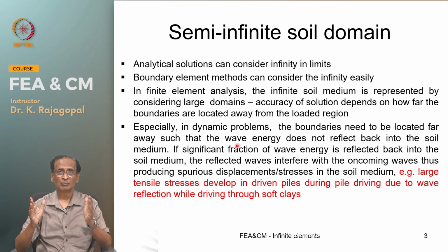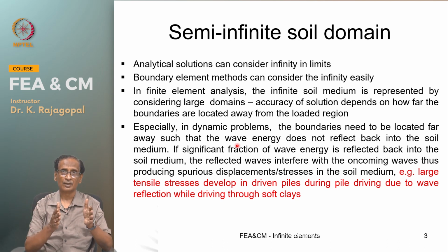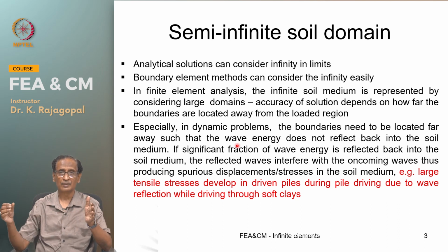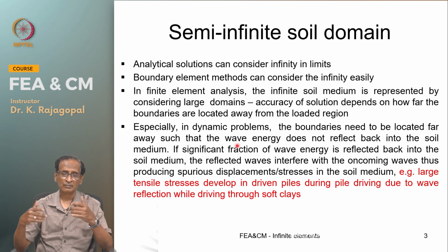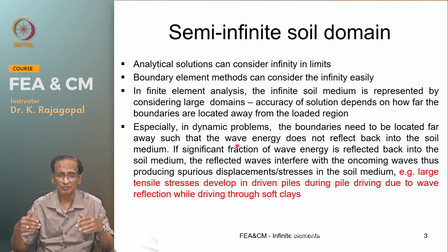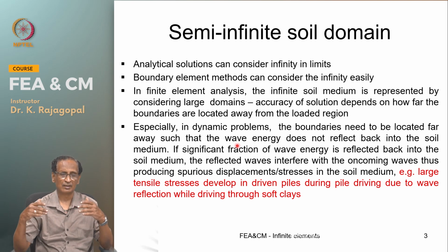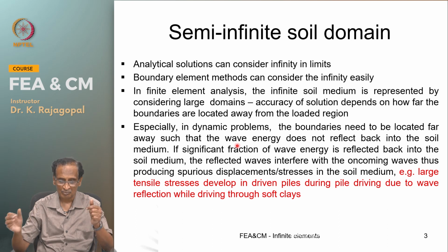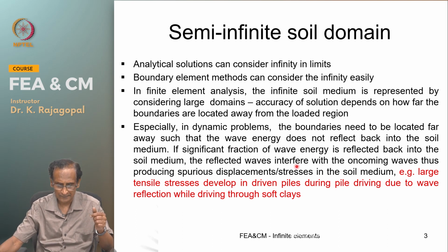But if you place the boundary too close, also you will have a problem, you will have some numerical influence, like your waves may be propagating. Once they reach the rigid end, they will reflect back, and then your oncoming wave and the reflected wave might interact, and they might produce some other extraneous stress condition within the soil, and that is also not correct.